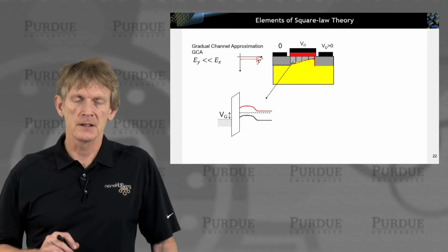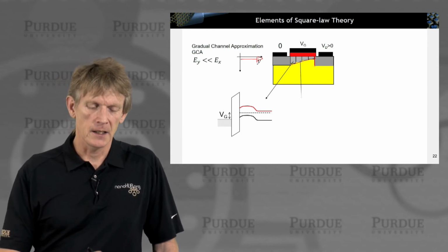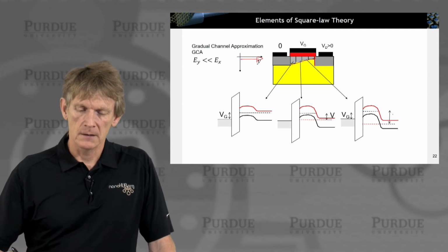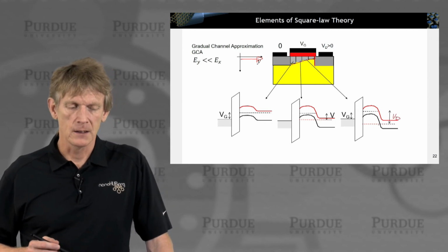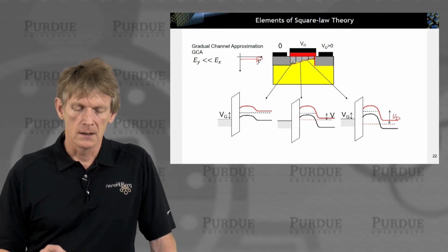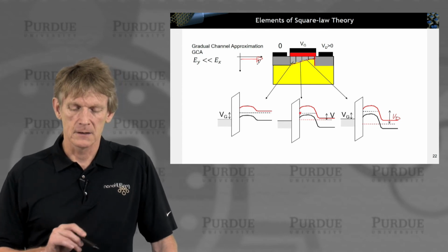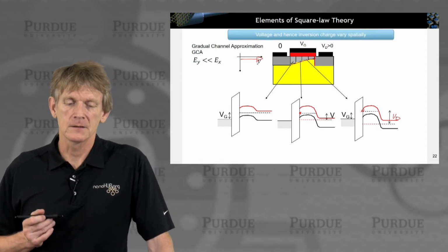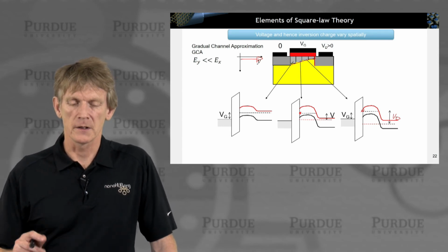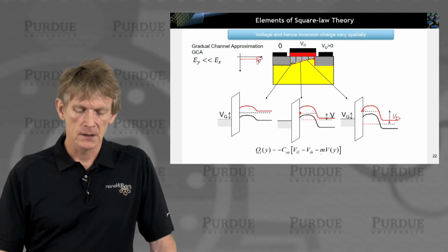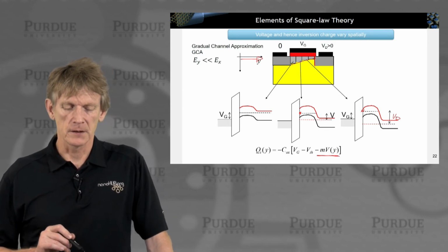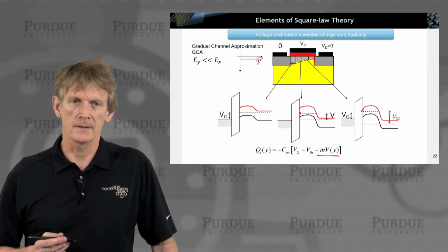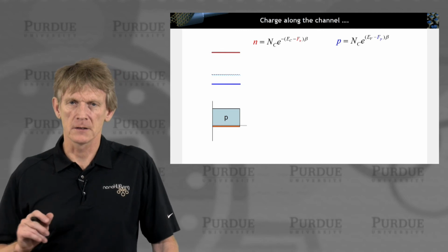All right. So let's sketch these potentials again, as we did at the entrance of the channel and roughly the middle of the channel and the tail end of the channel. So you've separated, this is the drain voltage effectively, you've separated the quasi-Fermi levels for the electrons here in the channel versus the overall drain. Okay, so the voltage and hence the inversion charge vary spatially, okay? So the inversion charge needs to be accounted for. That means this voltage that we apply in our charge model to calculate the charge is now spatially varying as a function of y, okay? Y is the direction along the channel.